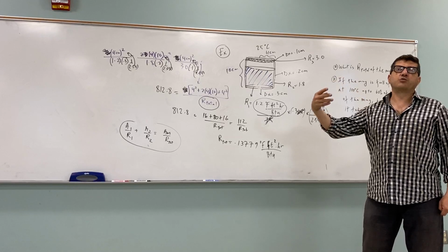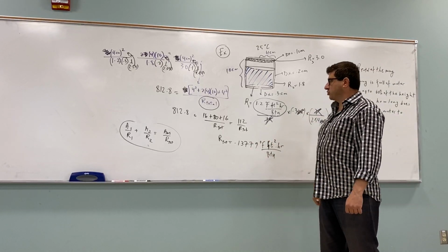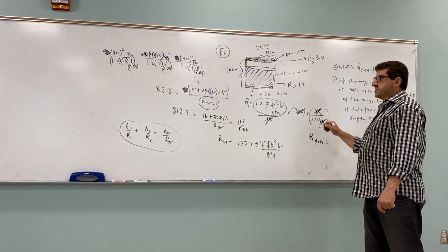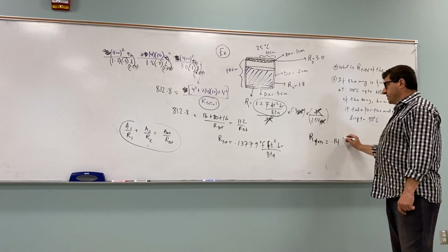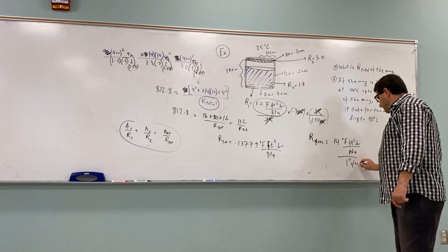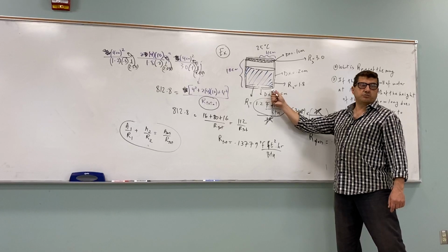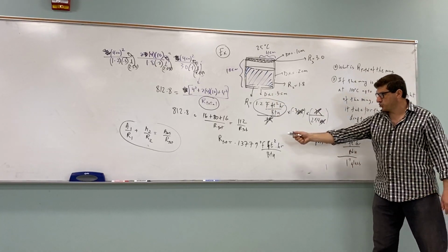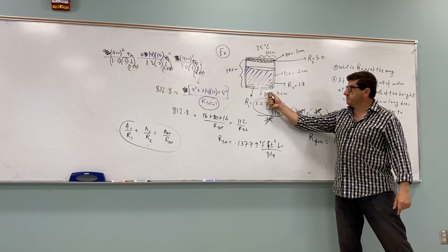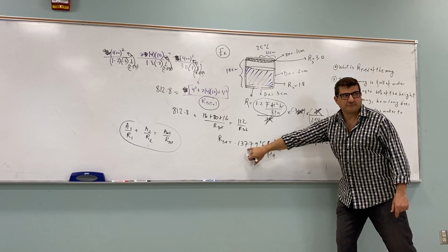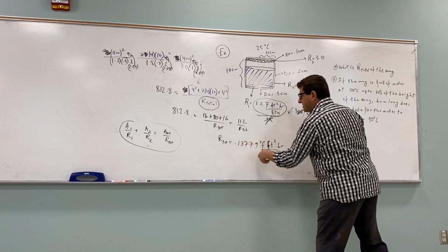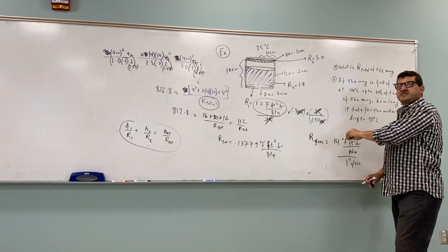In other words, we got rid of the normalized per 1 inch factor, and we said that's the total R total. Remember that we said earlier, glass is not a very good insulator. Remember I said the table was 0.14. But that one was in units of Fahrenheit feet squared hour per BTU, per 1 inch of glass. Of course our thicknesses are less than 1 inch, a lot less. So it makes sense that our total is about 0.14, but even with thinner. If the material of the mug was much thicker, our R would have been much bigger than glass, so our mug would have been a better insulator than glass. That's why this is the R total, including the thickness of the mug. That's already included. You get the idea?